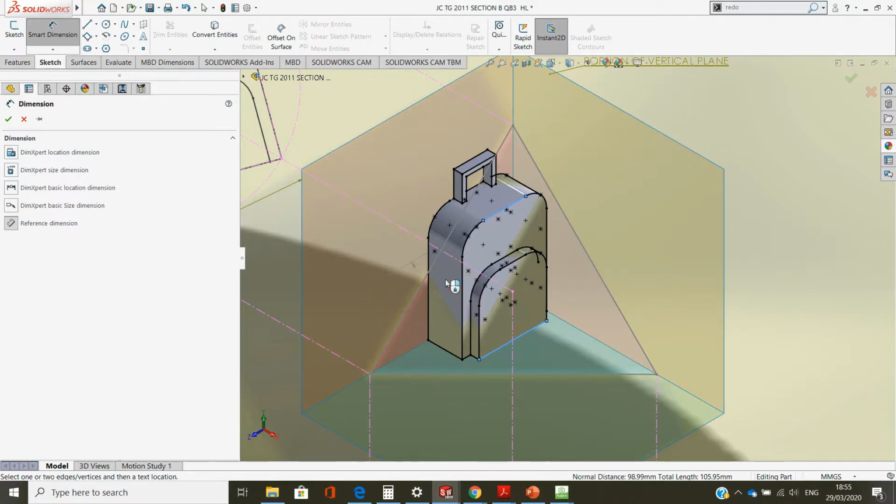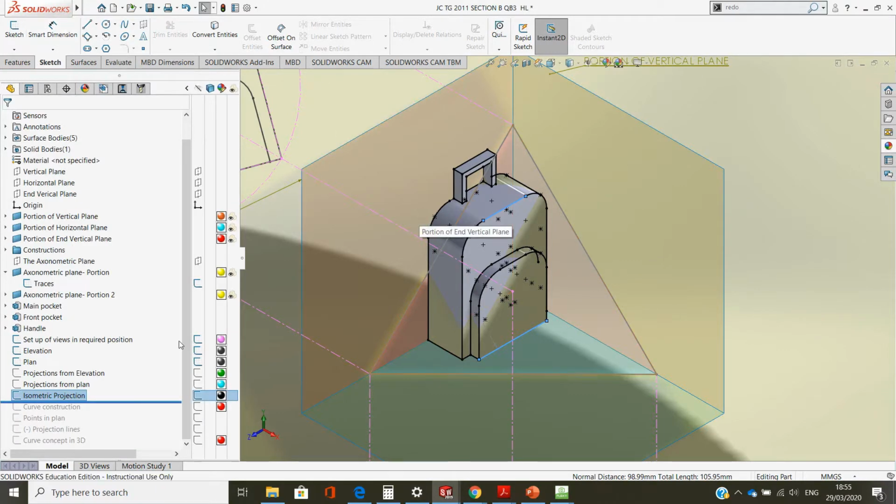Whereas in the axonometric view, if I dimension this here, okay, on the drawn it will be shorter, all right. On the drawn it'll be much shorter. Well, that's how isometric projection works. It draws a foreshortened view of the object.